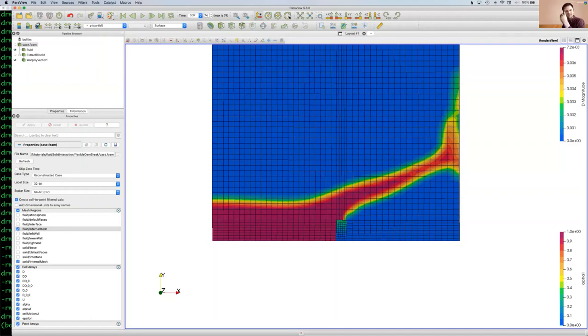I also spent some time in Texas, and the group there were using it to model fracking. So I see the group is still publishing and working on that code using OpenFOAM. So it is possible to model fracturing, and there is something called crack FE mesh. There is a tutorial in Solids4foam where it just takes a beam and pulls it apart, and then the mesh splits in half. So you can actually model that.